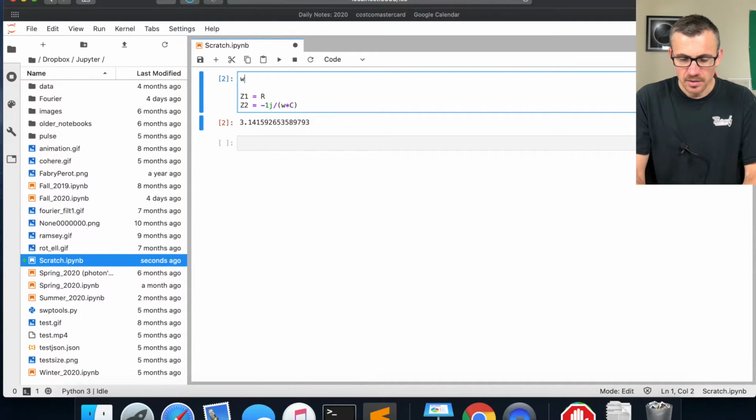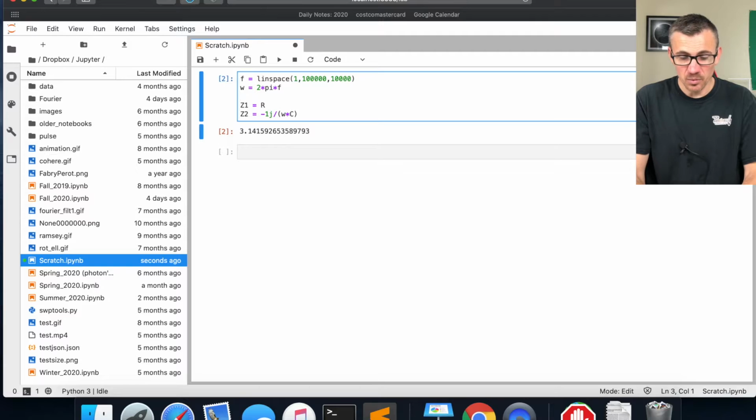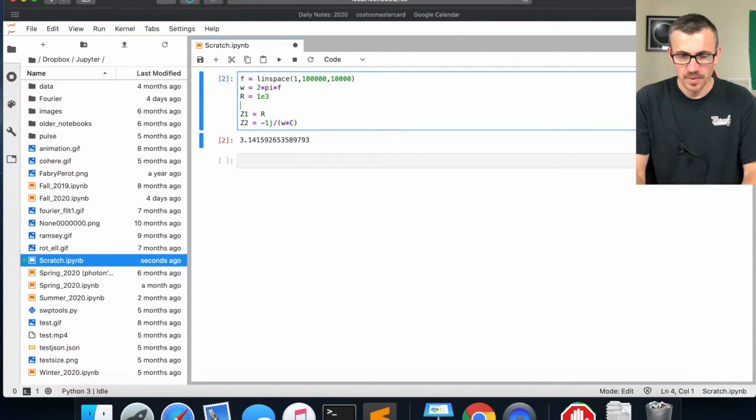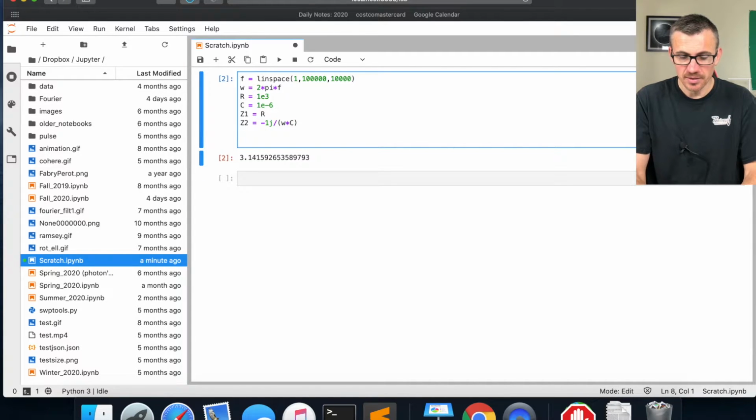All right, so let's give it some frequencies. Let's say omega is anywhere between, I don't know, a hertz and 10,000 hertz, and we'll give it a lot of points. Call that the frequencies. Resistance, let's make it a kilo ohm. Capacitance, let's make it a microfarad. And see what we get. So our frequency response G is equal to, just from our formula, Z2 over Z1 plus Z2.